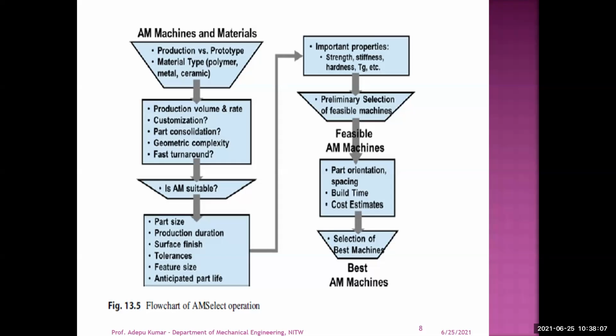For example, horizontal, vertical, or mixed horizontal and vertical, or some hatch patterns which people are also working on. So different hatch patterns, for example, square, hexagonal, and honeycomb structures. These structures will give additional properties like strength and stiffness. So depending upon the orientation, the properties are also going to change. And what is the spacing between the two layers? How much spacing can be given?